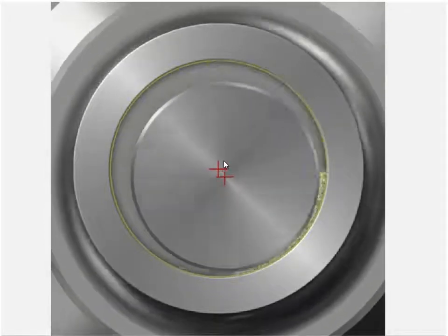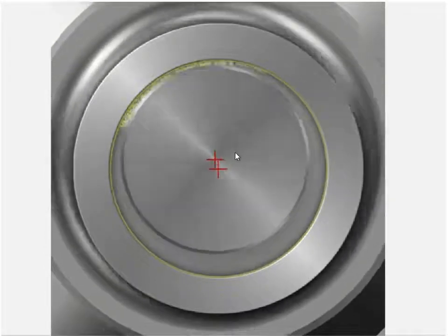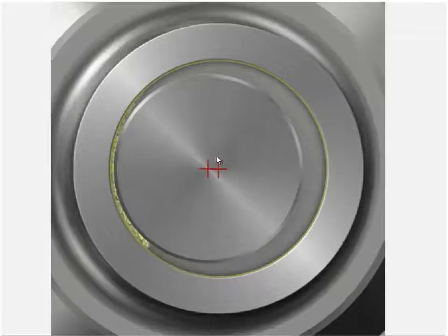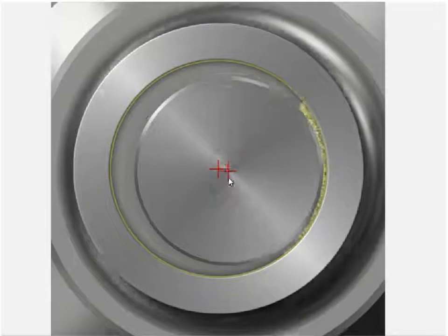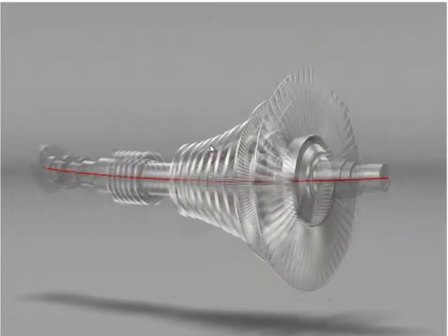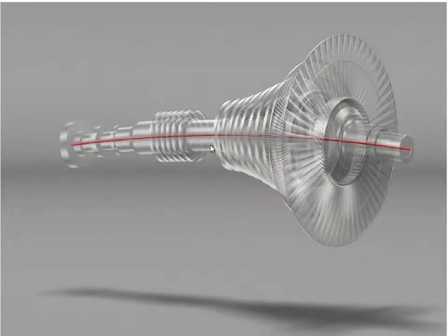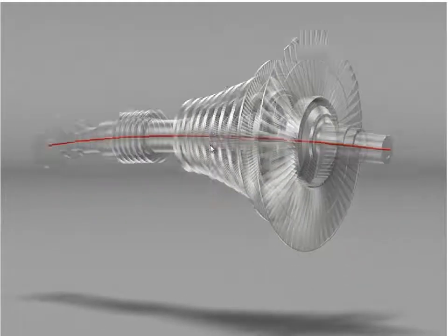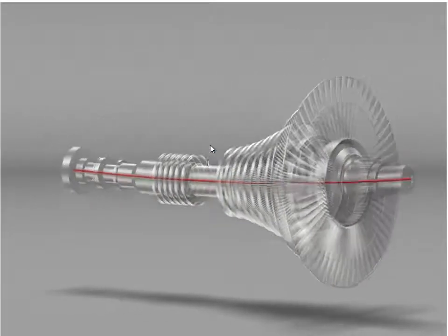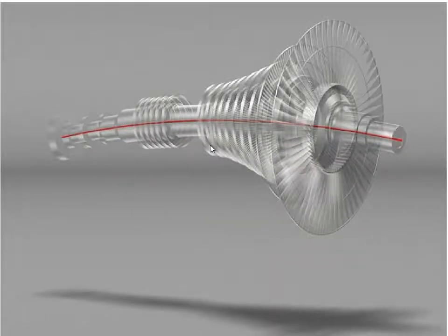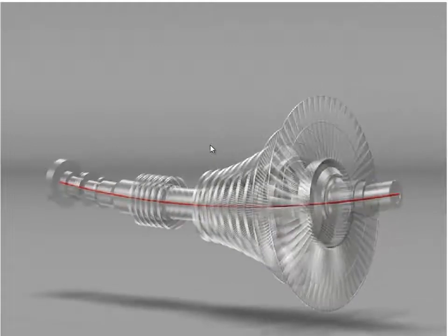It can't be any higher at this particular location. There can't be any more motion because it would start wearing away the bearing. But this is the sort of thing we'd like. We want to know in essence what the shaft is doing, what the center of the shaft is doing, because there are other faults. In addition to unbalance and misalignment and preload and these sorts of faults, we're interested in the rotor dynamics as well, particularly as we go through the critical speeds. So in this instance, exaggerated, but that's the motion at the first critical, let's say.